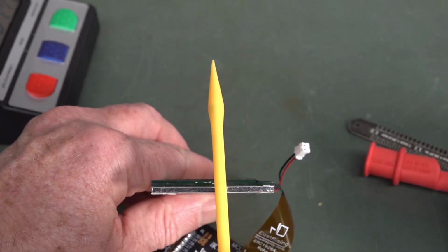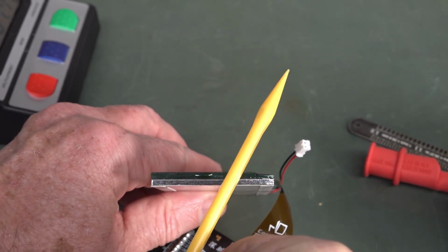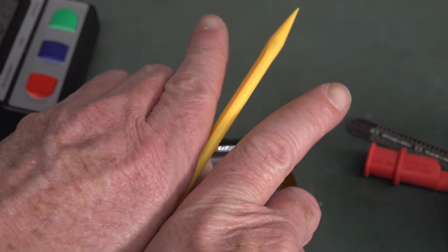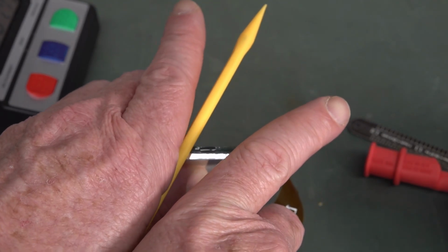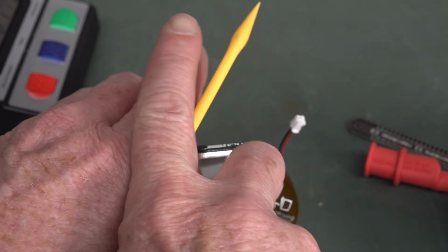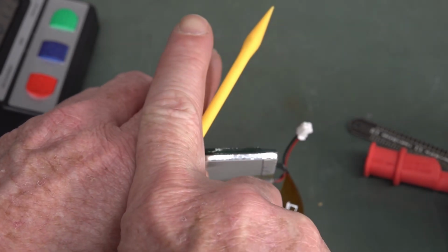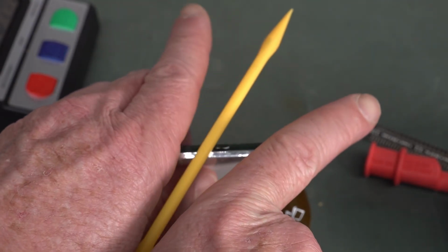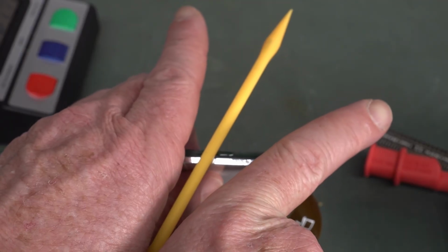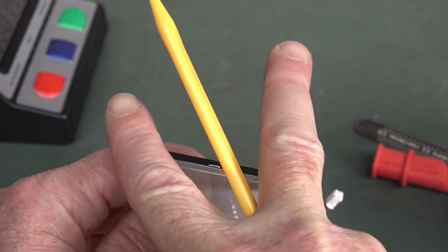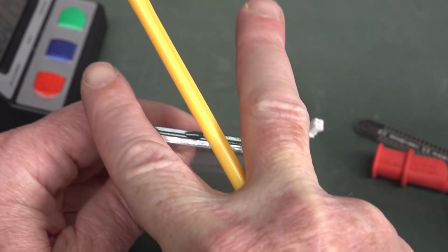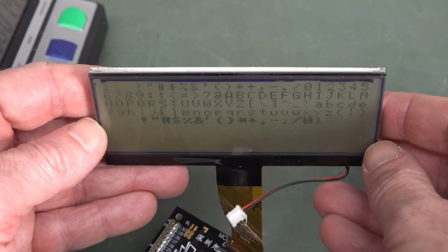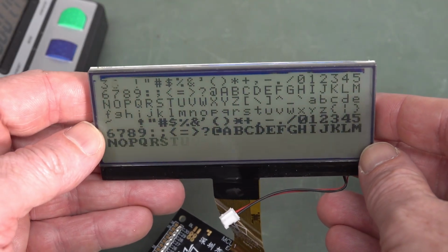And on top of the bias angle, which say it's at 6 o'clock from the bottom, you will then have the viewing angle. Please excuse the crudity of the model, I didn't have time to build a scale one or to paint it. The viewing angle is then plus or minus a certain number of degrees. Say you've got a 60-degree viewing angle, then it would be plus or minus 30 degrees from that bias angle. If it's 12 o'clock, then you'll have a viewing angle like that from the positive side. But this is the 6 o'clock one, and you can see this actually has quite a large viewing angle.